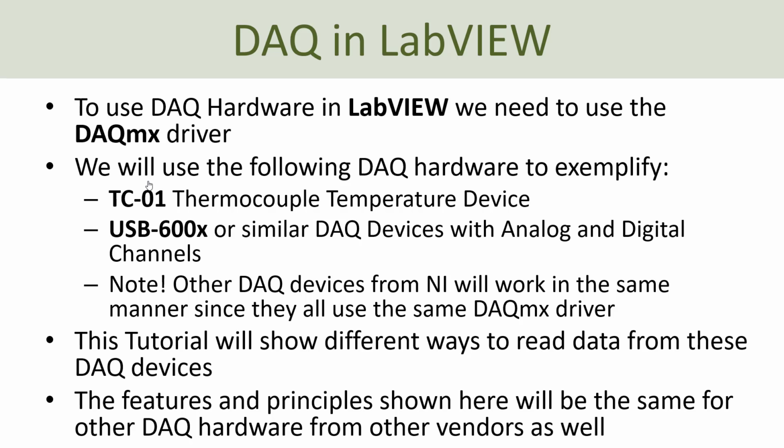So in order to use DAQ hardware in LabVIEW, we need to use this DAQmx driver. This DAQmx driver is free to use. You can download it for free from the internet, but of course you need a valid license of the LabVIEW programming environment. I will focus in this tutorial on the following DAQ hardware, because these are the devices I have here in my hand.